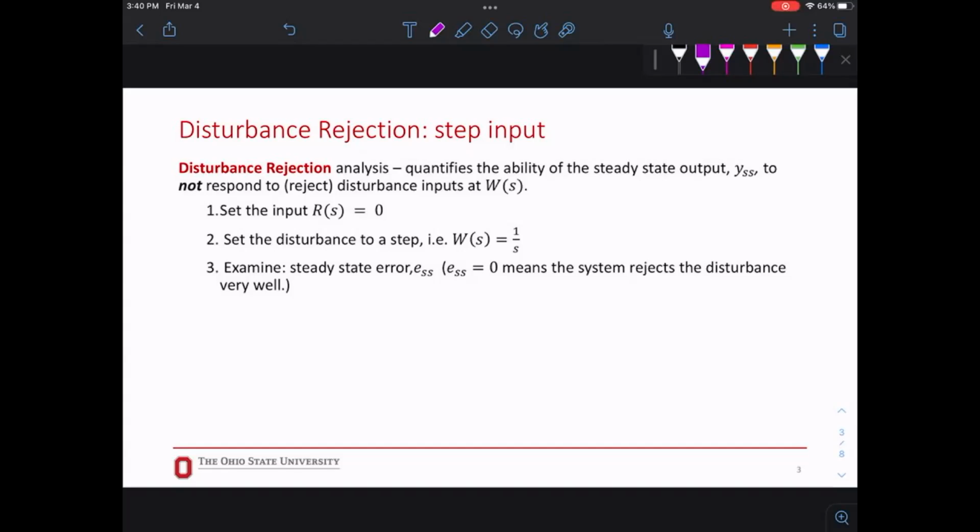Every time you calculate error, there was just input and output, right? And if there was a disturbance, I said assume the disturbance is 0. Now, what if the disturbance is not 0? What do we do? Do you remember these systems are LTI, right? So for a system that has disturbance and input, basically you have two inputs. How about we look at the behavior when we only have the actual input, then look at the system when we only have the disturbance as input. The combination of these two is going to be the response, because we can use superposition in an LTI system, right?